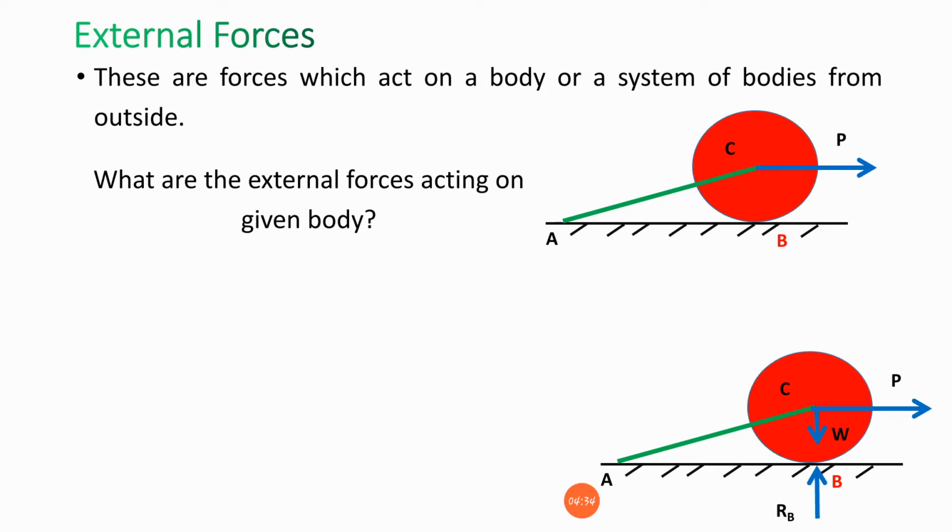It tries to oppose the weight of the body in the downward direction. That means here RB provides the restriction against movement in the downward direction, so a reaction force develops. AC also has tension, but that is included, since AC and the sphere are only one unit.